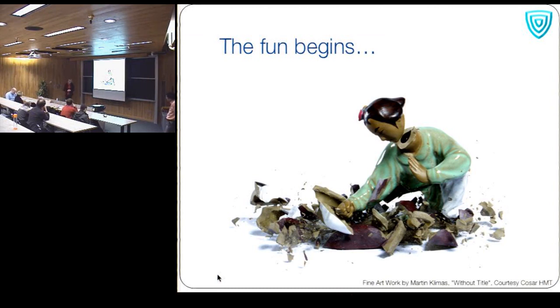So where the rate effect comes into play is under static loads, the big flaws tend to dictate what the strength is. So if you have a large flaw, the crack takes off, it's unstable, the sample's done. When you load it quickly, what happens is those big flaws activate cracks first, but those cracks are growing at this speed, and the load is cranking down on them.